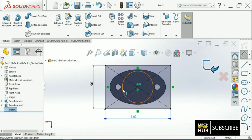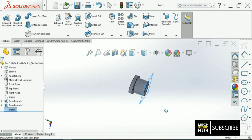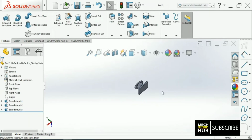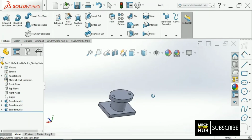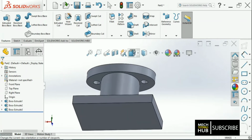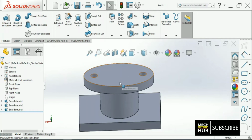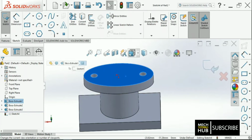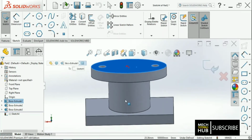Exit. Alright, now here material addition or extrusion is up to a distance of 15. 15, enter. This is done. This is the first component, part number 1, and there is a through hole from top to this particular face. For that, I'll select top face, sketcher, keep the model normal to the window,